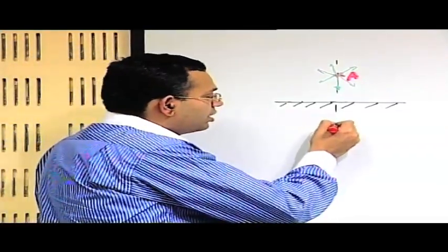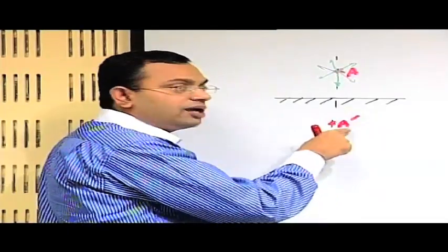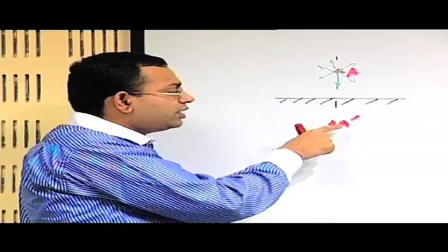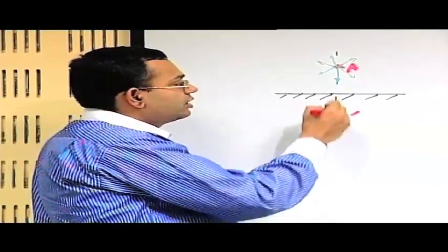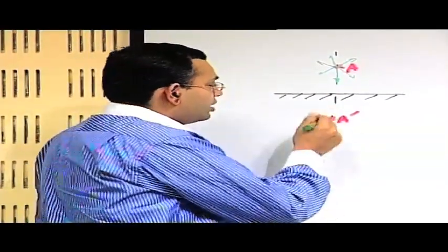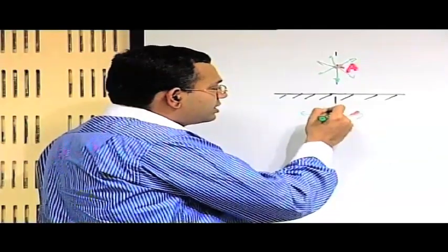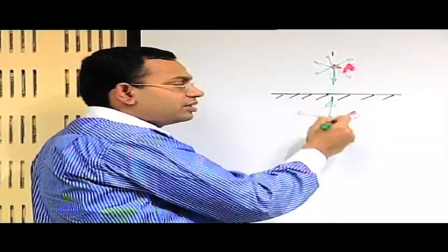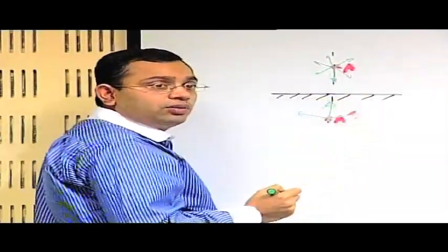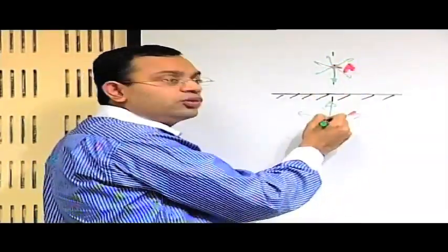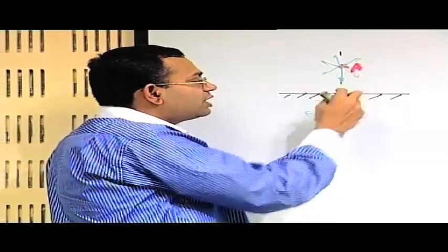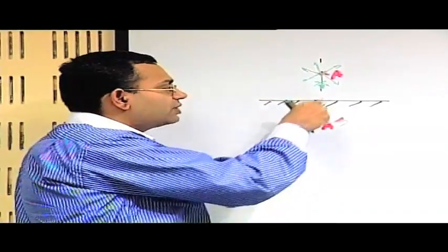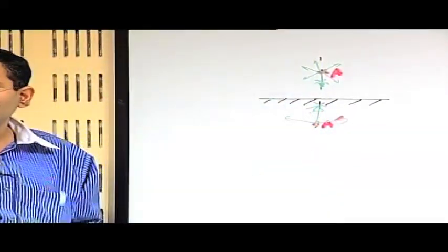Just think like this, it is a very common sense thing. Just like a reflection, you have an image source located at this point. It will also have its own radially diverging field, and one of the velocity directions is this, perpendicular to the wall. So if these two sources are of equal strength and located at equal distance from the wall, then these two effects will nullify each other to have a resultant normal component of velocity of 0 at the wall.